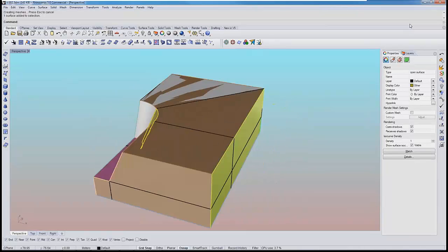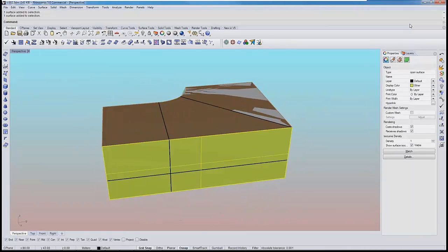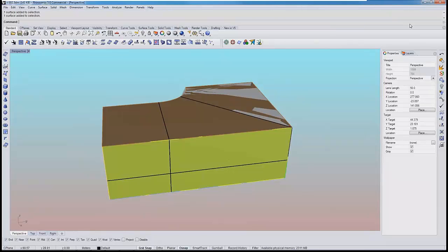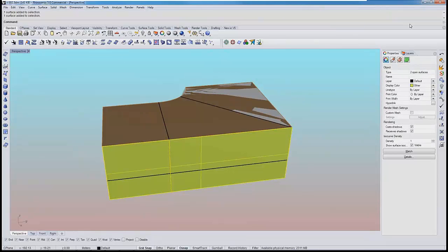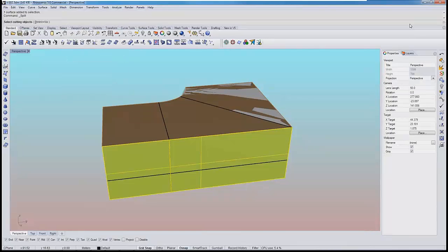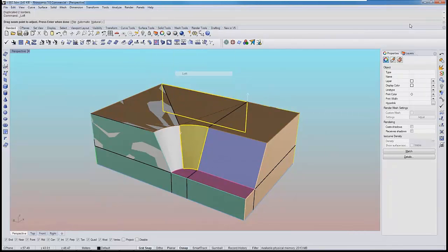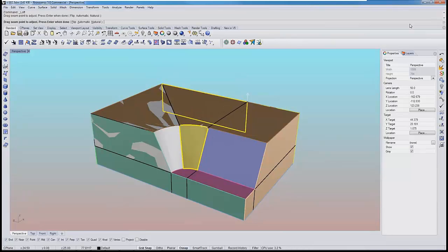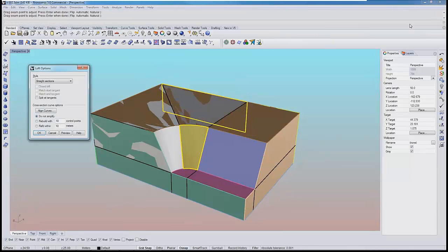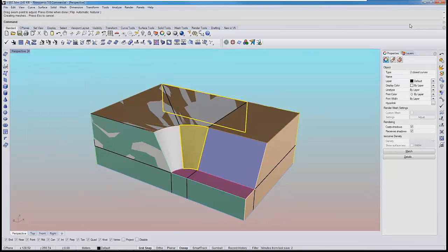Similarly, we are going to create the adjoining solid, again in a similar fashion, by cutting the opposing rectangle into four smaller bits, and rectangles are both selected. One rectangle here is selected, and the curved surface that is supposed to face it. We extract their boundaries, and we use the loft command. Again, we need to tell it to connect that point to that point. We have to physically drag that connection point and say, go ahead and create a lofted surface.